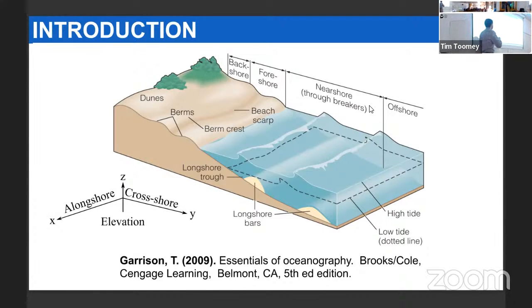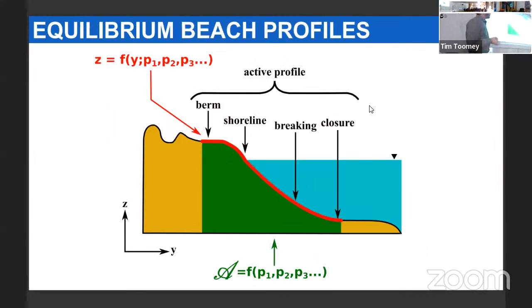In order to simplify it, instead of taking the whole two-dimensional map, we could take transects perpendicular to the shoreline and average them. So now we are talking about equilibrium beach profiles. We are interested in this zone, the one under the effects of incoming waves and other marine forcing. This is what we call the active profile, where this forcing is capable of changing the bed because of sediment mobilization.